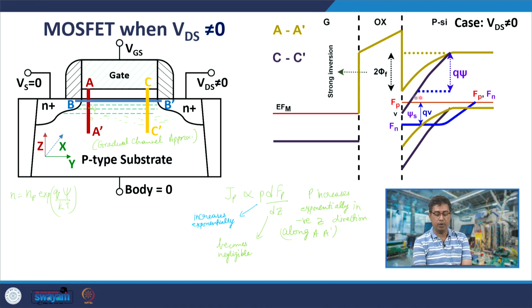So, therefore, since there is almost 0 electron current density in equilibrium condition or in quasi-equilibrium condition, and it is almost like quasi-equilibrium condition at the source edge of the channel, the quasi-Fermi levels of holes and electrons would align and match at the interface.